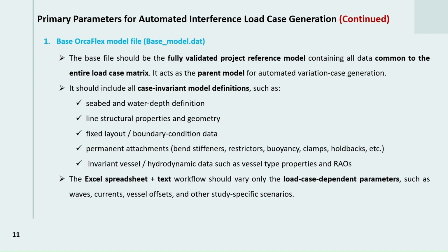The base OrcaFlex model file should be the fully validated project reference model. It should contain all data that are common to the full load case matrix. This means the base model acts as the parent model for automated variation case generation.